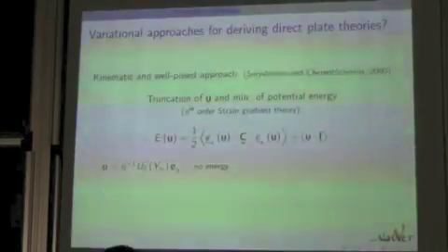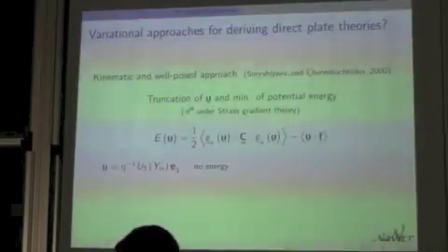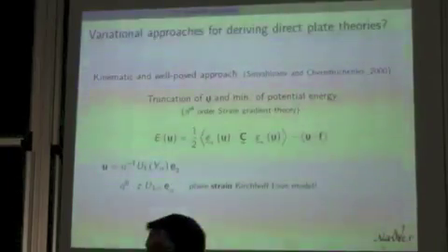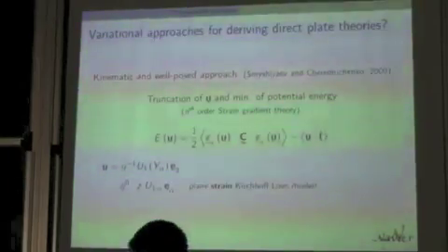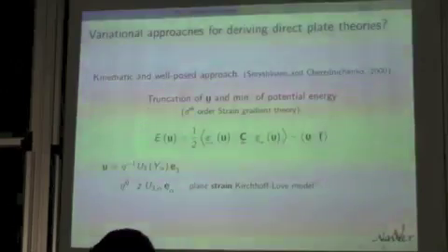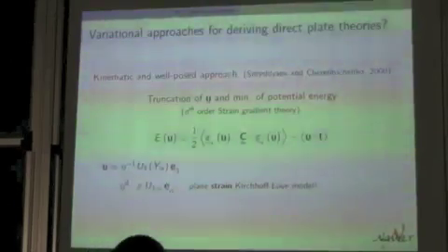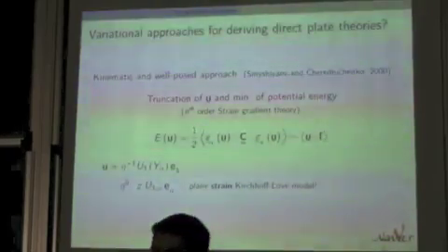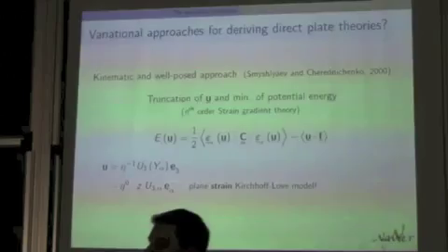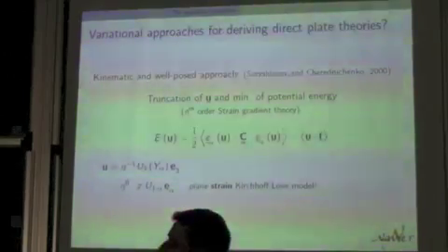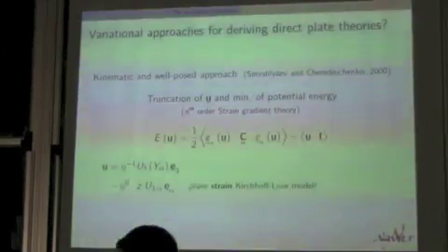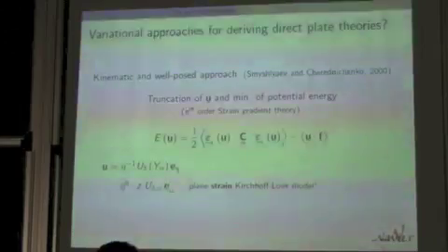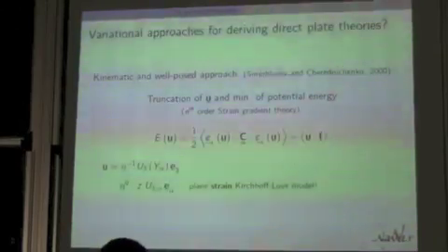If I take the first term, there is no energy, it's rigid. Okay, second term, you have this rotation in addition. Then, if you do that, we will have a plane strain Kirchhoff law model. Actually, the model derived by Kirchhoff, with his assumption of no out-of-plane displacement. But we understand that this is not physically consistent. Everybody wants a plane stress plate model. Okay, so this doesn't work, and we don't have transverse shear effect anyway.